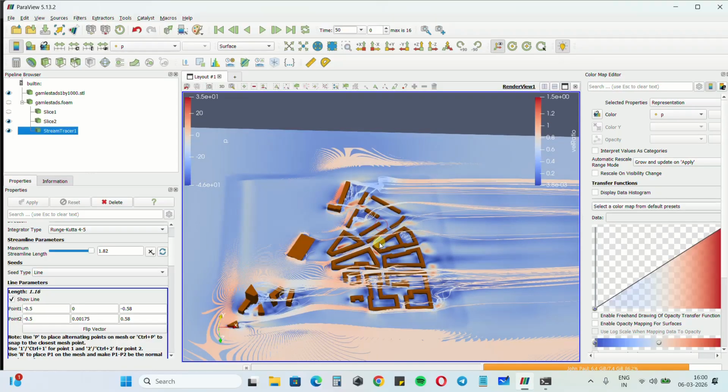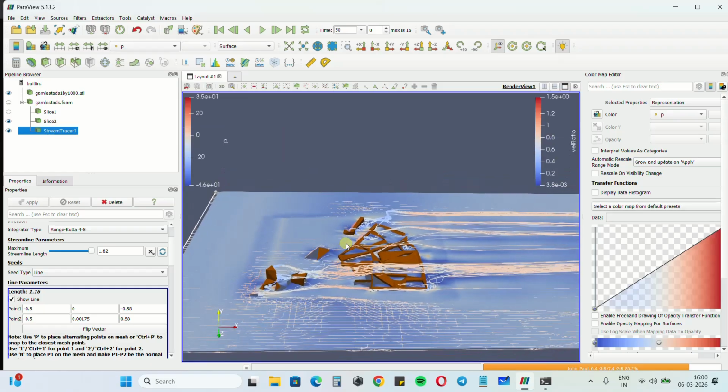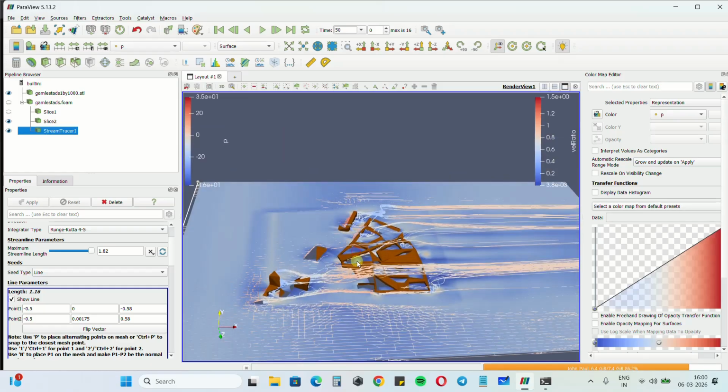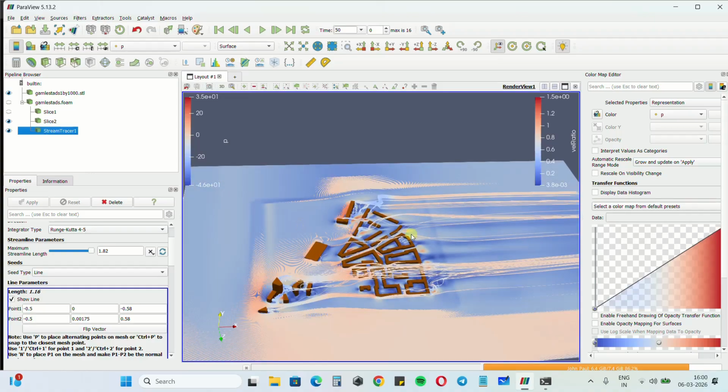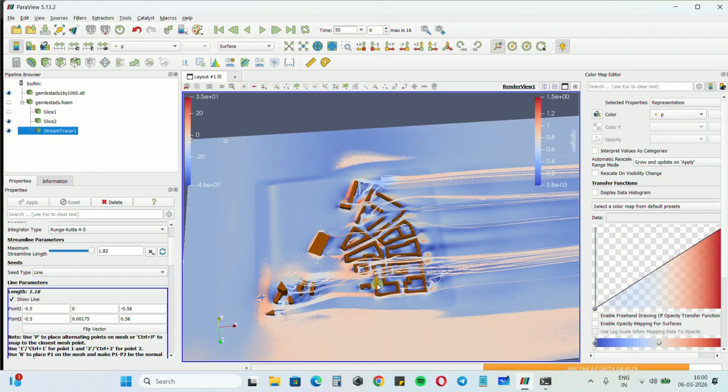So I think this is really good. You can get a lot of information from here. I just applied the validated atmospheric boundary layer flow modeling from my previous simulation to this geometry, the city block, and made use of it to study the plan of the city. We had a lot of assumptions here. I haven't considered thermal effects, and I haven't considered the vegetation. So that's the next step.